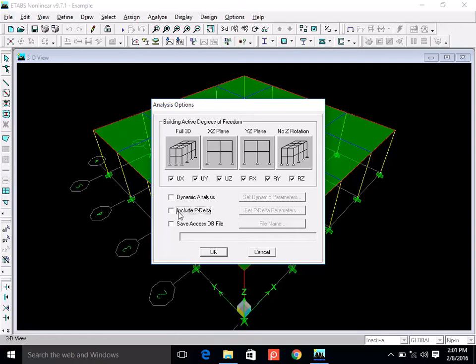I think there is another thing before. What was that? Earthquake. Load combination type. Mass. Yes, iterative. That was special seismic effect and the masking. Okay. So as a beginner, I am unchecking this option. So on this panel, we have just make sure that we are doing full 3D analysis by clicking this option.